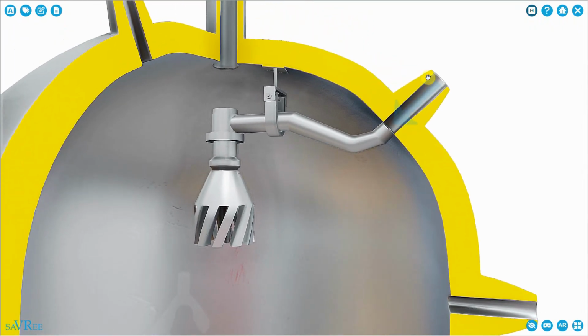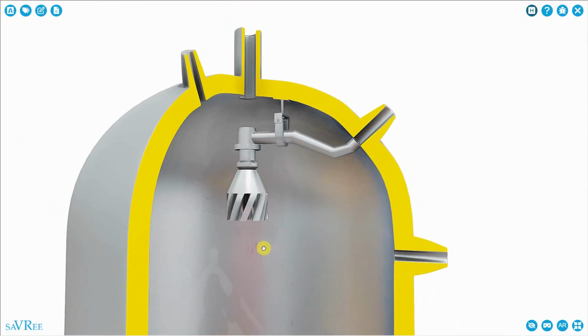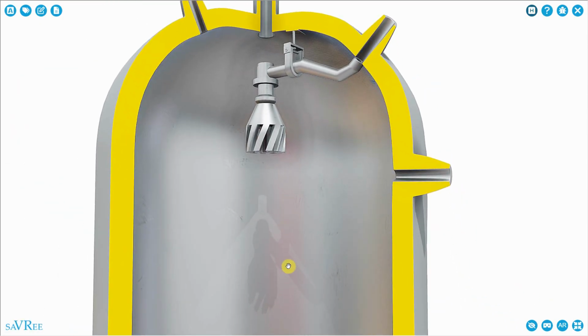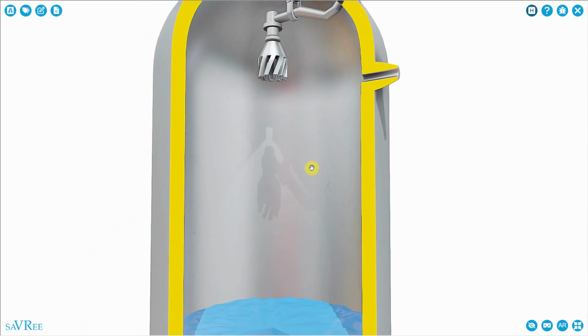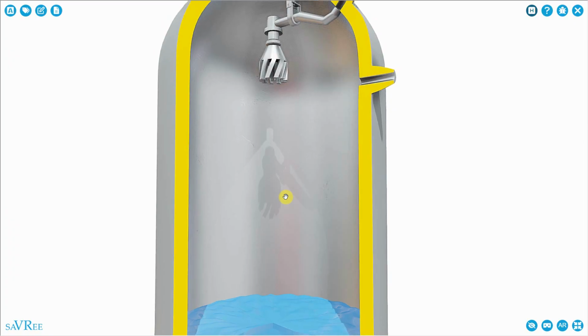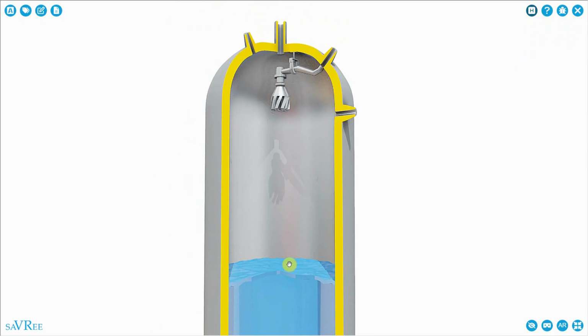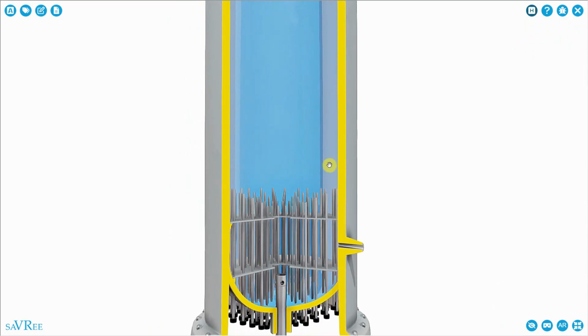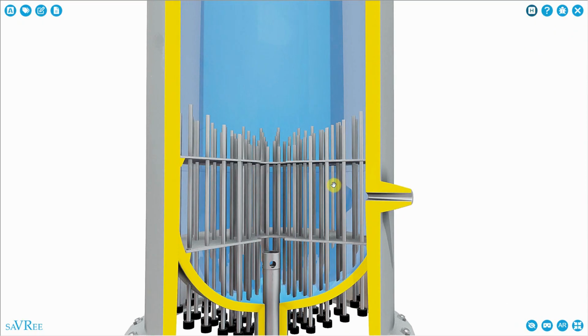This is actually from our primary coolant cold leg, where we spray the cooler water, the colder water, into the top of the pressurizer. And we do this because we want some of the steam to condense and turn back into water. We call that changing state or changing phase. When the steam condenses, the pressure in the system reduces. When we heat more of the primary coolant and it turns to steam, the pressure in the system increases.